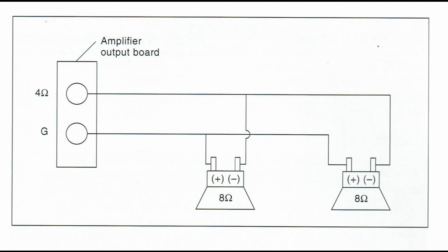In other words, you connect a speaker system of specific impedance to a power amp output with that same number, as shown here. Sometimes it's desirable or necessary to drive more than one speaker with a single amplifier. This can be accomplished by wiring the speakers in parallel, as seen with that image.